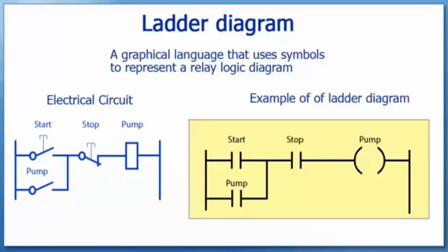Any rung must be connected to an output, but it isn't necessary to have an input, just the connection to the left power rail. The program is executed starting at the top, completing one rung from left to right, one rung after another. When the program is connected to the PLC, you will see changes in color to the symbols depending on whether the inputs and outputs are on or off. It is possible to view the program like an electrical circuit and fault find as if you were working on a real electrical circuit.